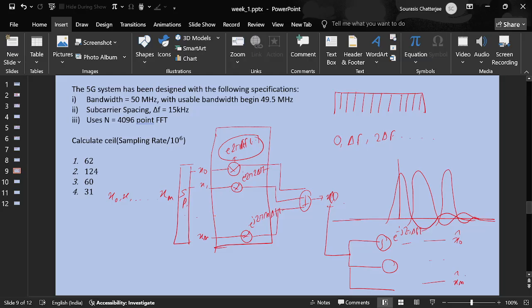Can you just clarify the orthogonality part once? What exactly do you mean by that? Is that the orthogonality between subcarriers you are referring to? Yeah. Okay, that would cause you inter-carrier interference when the subcarriers overlap with each other. But cyclic prefix, as the person pointed out, is because of multipath, true. But I'd like to understand in a bit more depth how exactly multipath creates an issue for you. Can you go a bit deeper?